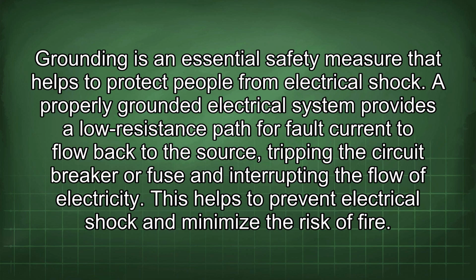A properly grounded electrical system provides a low resistance path for fault current to flow back to the source, tripping the circuit breaker or fuse and interrupting the flow of electricity. This helps to prevent electrical shock and minimize the risk of fire.